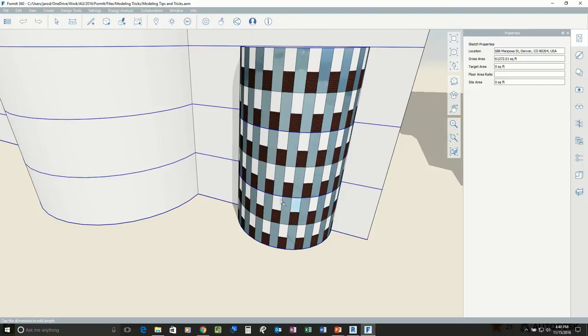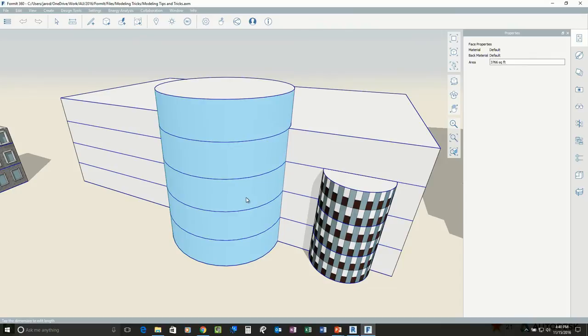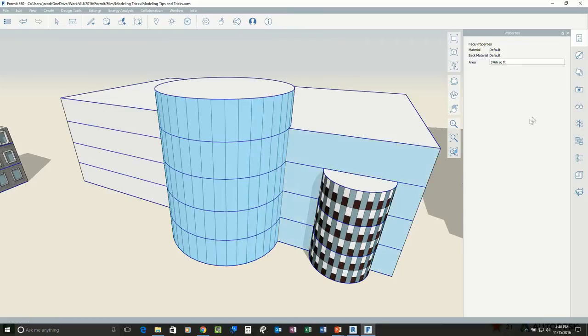So this whole process that you're seeing here, this is how I came about doing this. So it's not overly hard. It's just at times it gets tedious, but basically you pick on the surface, you say, hey, I want to facet it. You can see how it breaks it up automatically. The other beauty is noticing that when I pick on it, it shows me the total square footage. So that's kind of cool. That's giving me some feedback about punch openings and maybe glaze ratio.